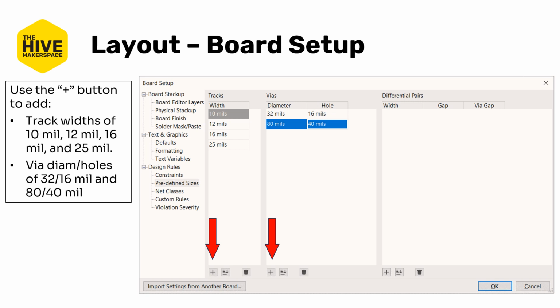The parameter diameter for holes and vias refers to the diameter of the hole plus the annular ring. It's generally a good starting point to have the ring diameter, that is the diameter parameter here, be about twice the hole diameter. And larger diameters, meaning larger annular rings, can make soldering a little bit easier. The default values that I've provided here are not required by anything. They're just defaults that I personally like.